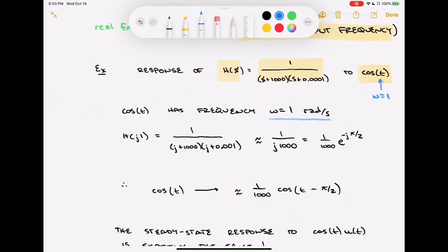If you look on the omega axis in the s-plane, this is just where sinusoids live. So H of j1 is where the 1 rad per second sinusoid information resides. So let's go ahead and look at H of j1. What does that involve? It requires us to take that s value and look at H of s, and we're going to let s equal j omega, or in this case, j1, because j1 is the frequency of interest.